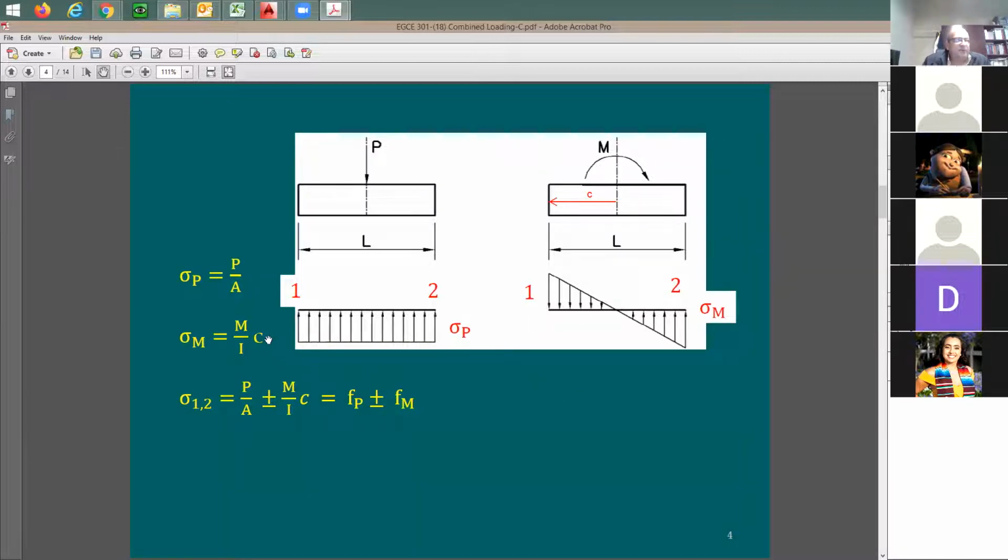And here's the stress equation. If I'm given this stress distribution, can I do integration to find the moment? I'm going to say yes. Very similar to what we have done in the force or the couple method, I'm going to do integration for this triangular distribution block. The same thing here. I'm going to have tension and compression, multiply this by the moment arm, and between the two, you get the moment.